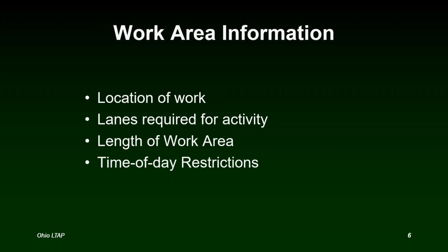Also, time of day restrictions. That's talking about whether you are going to be working during one of the rush hours, maybe the AM peak hours of traffic or the PM peak hours of traffic? If you're working on a residential street or low volume street, that might not have an impact on what you're doing that day. But if you're working on a major arterial or a freeway, and it's not an emergency, it's just routine roadway maintenance activity, then we really don't want you out there between 7 to 9 a.m. and 4 to 6 p.m.